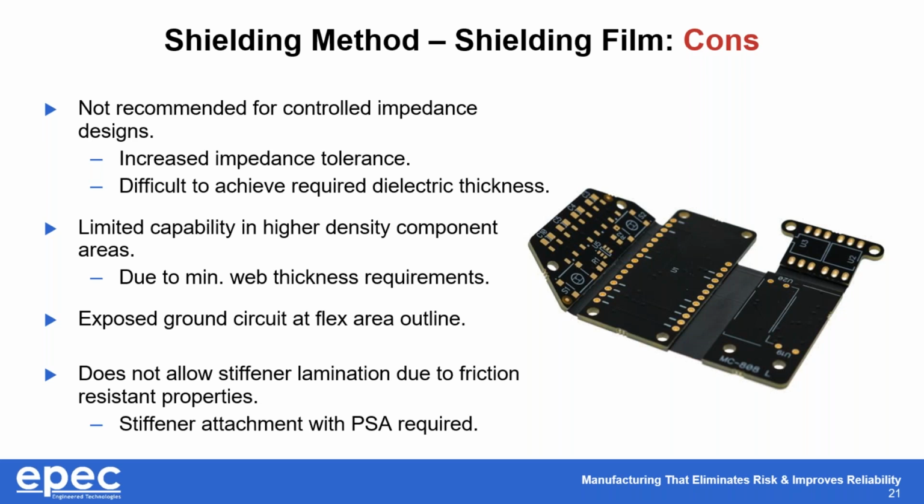In designs where the shields have to extend underneath the stiffeners, what we'll do is attach them with a PSA. Again, that's an effective methodology. We'll typically use a high bond strength 3M product to achieve that, so it can be done.